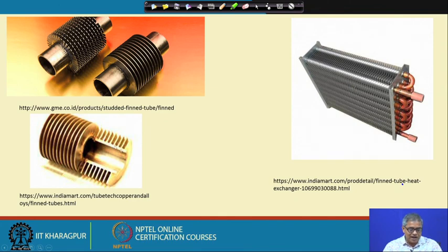Now, this design is all right, but here you see while making this kind of a component, there will be a lot of material taken out or cut out or wasted, quote unquote wasted, because we have to make these slots between the fins. On the other hand, what you can have, the tube is made of a material and a separate kind of a fin or fin surface you can attach on it. So, that you can find in these two designs.